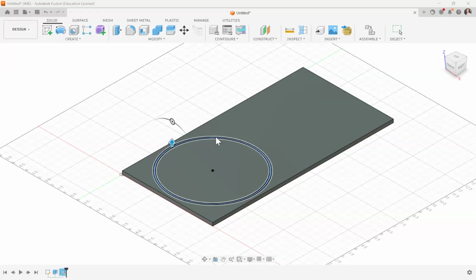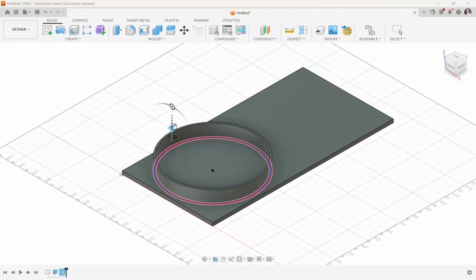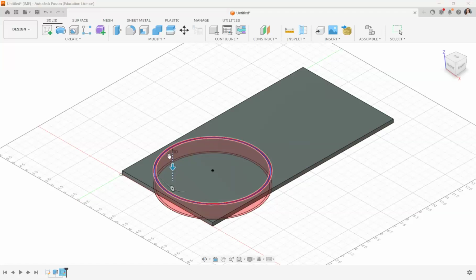So now we have the arrow again. Now, do we want to pull it up like this? No, why not? Because we want to cut the material away. So we want to go negative. But do we want to go down an inch? No, we want to just cut through the stock. If you were to do that, minus 1 inch, you would cut through the machine and you would break the tool and you would break the machine. So if we just want to cut through the stock itself, what is this distance that we should make it?